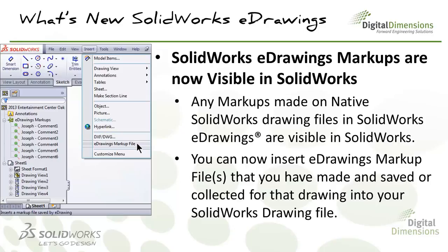Well, now in eDrawings 2013 we'll have the ability to see those markups right inside of SolidWorks on top of the drawing that we need to modify. In addition to that, if you had sent out an eDrawing file to get feedback on, you can take the eDrawing markup files that people save out of eDrawings, and you can now insert those eDrawing markup files right into your SolidWorks drawing inside of SolidWorks. So I think this new enhancement of making eDrawing markups visible in our SolidWorks drawing files is going to make eDrawing markup capability much more valuable.